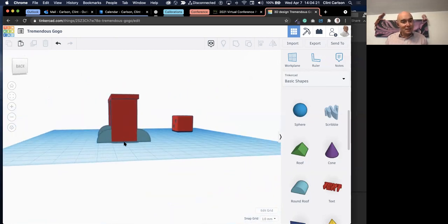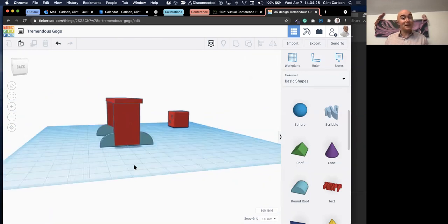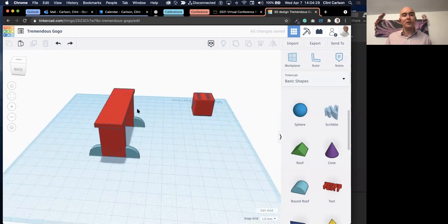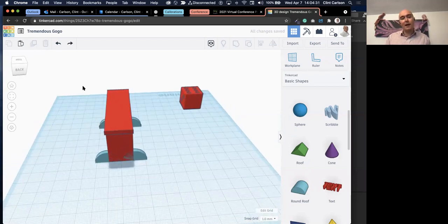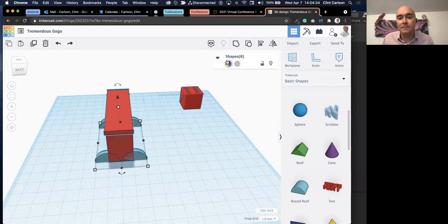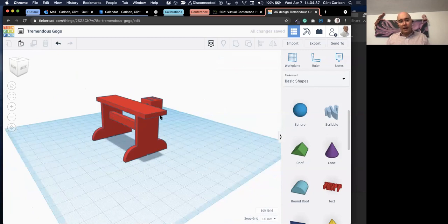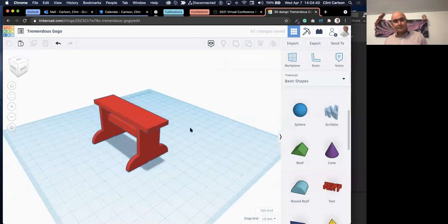And we can see there's a little glitch down here where the leg didn't quite come all the way down to the ground. That is something I would definitely want to clean up before I send it to a 3D printer or somebody for feedback. So we can do that. So let's change that back. I do want it to all keep one color. And I'm going to select this die, remove it from here. So I just selected it and deleted it.